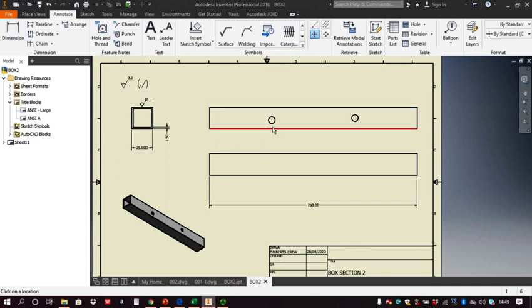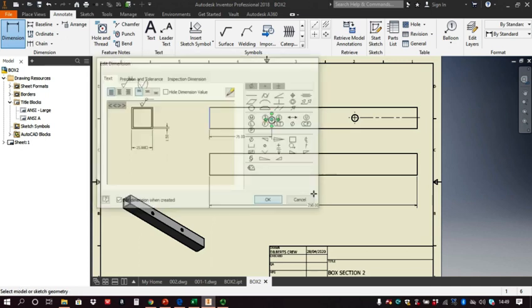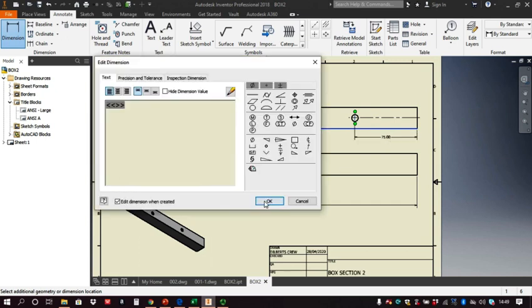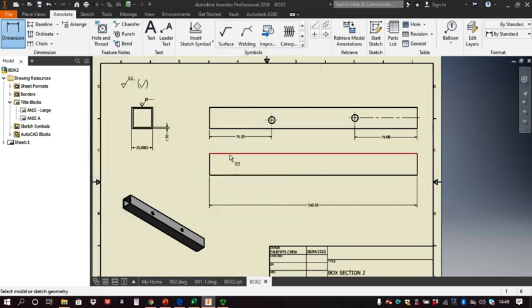My first protocol that I nearly always forget to do should be center lines, and from there to show that it's in the center, create. Okay, so now I can dimension that a lot easier because I can just go from there to there, 75 millimeters. I can go from there to there, 75 millimeters. There is no need to do that one because we've already said it's in the center, and this one is at 10 millimeters there. Okay.